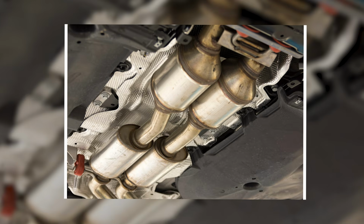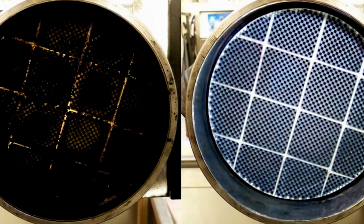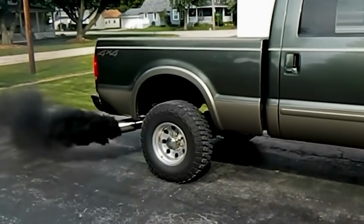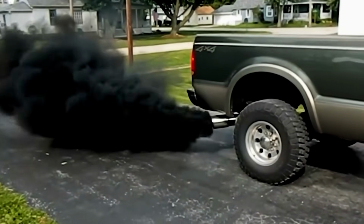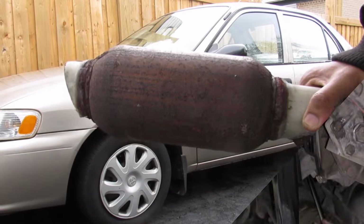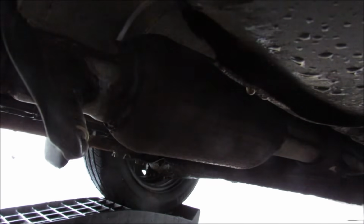During the inspection, if you notice a heavy black residue around the tailpipe, it could indicate that the catalytic converter is not effectively converting harmful gases, leading to increased emissions. Interpreting these results is straightforward. Minimal soot suggests a healthy converter, while excessive soot points to a dirty or failing unit.